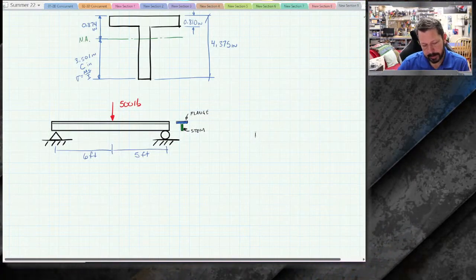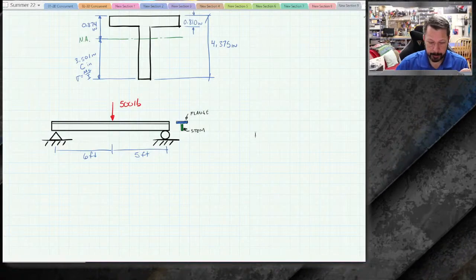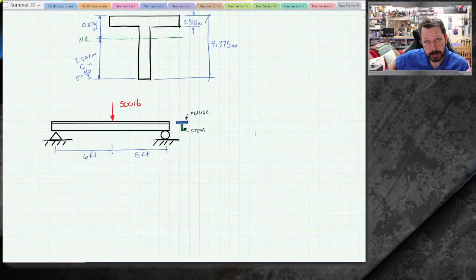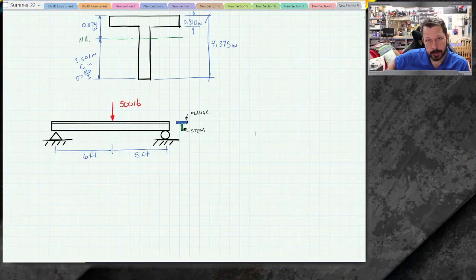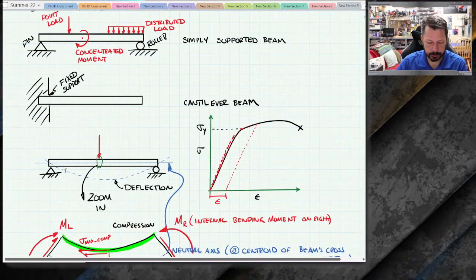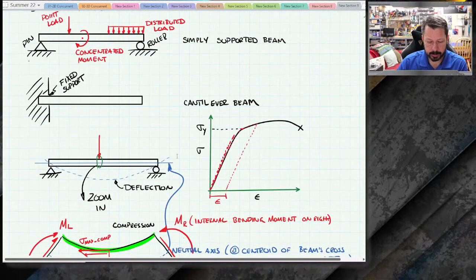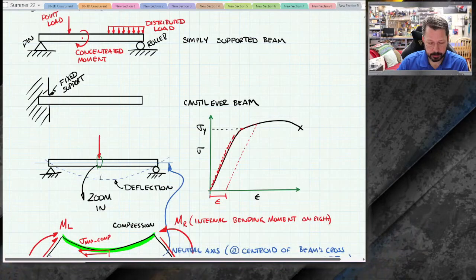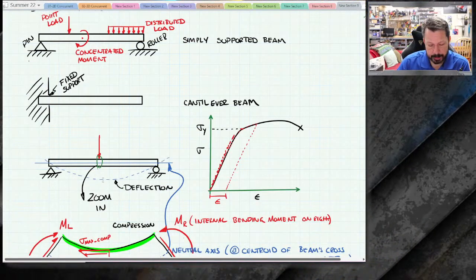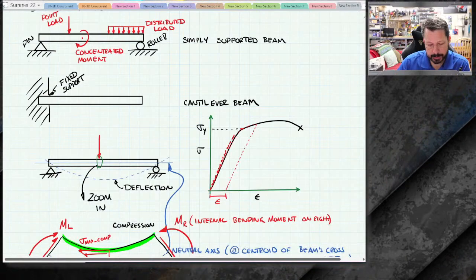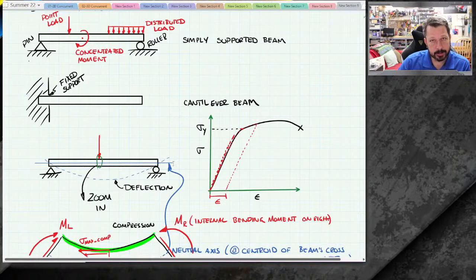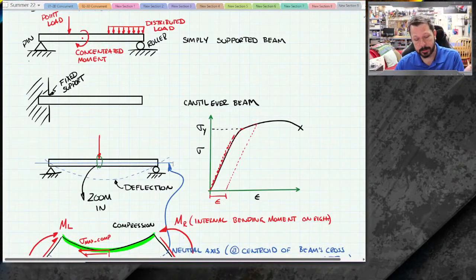When you have beams in bending, the bending stress, the flexural stress, changes from one end of the beam to the other. You know, if I look at this little sample where I drew the dotted blue line, there's more bending happening in the middle, less bending happening at the edges where it's supported. And so the bending stress is not consistent from one end to the other.